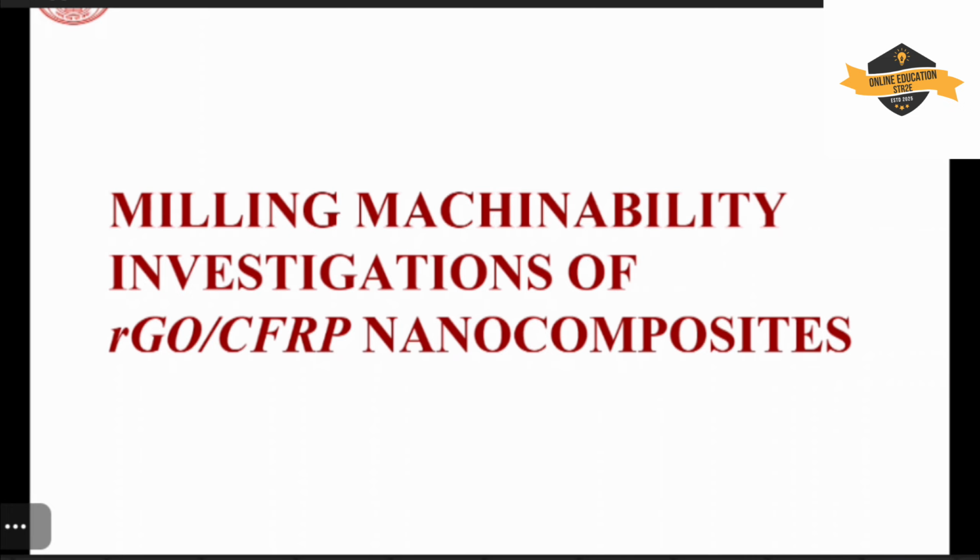Synthesis and development. After that, we have tested the material. The tensile test is there, the izod impact test is there, and different types of advanced characterization are there, in which TGA, DMA, FTIR, XRD we have performed.